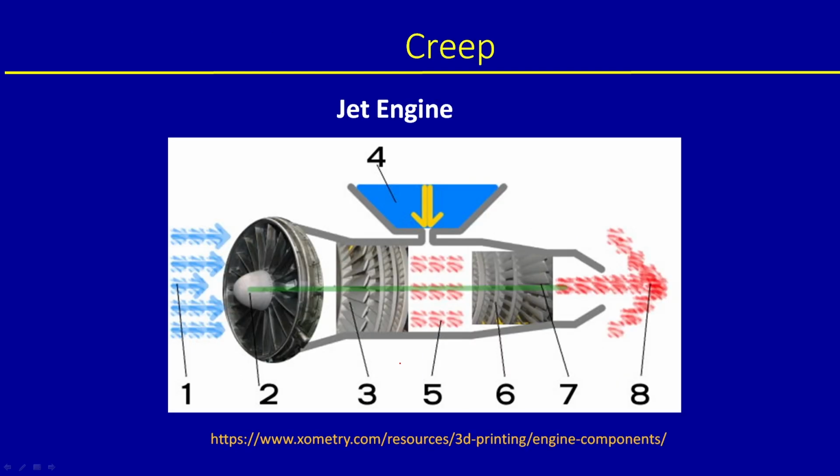The last I talked about creep, right? Creep is time dependent high temperature deformation. Well, it can be room temperature also. Some metals like lead, tin, they show creep behavior at room temperature because their melting temperature is very low.